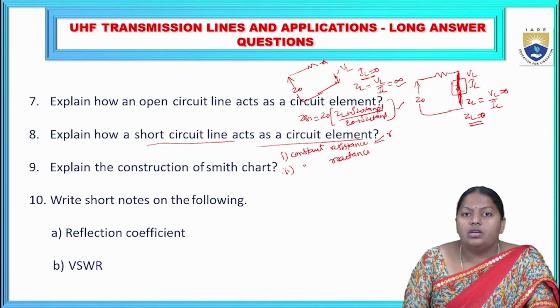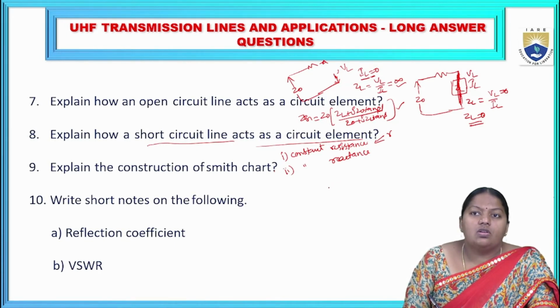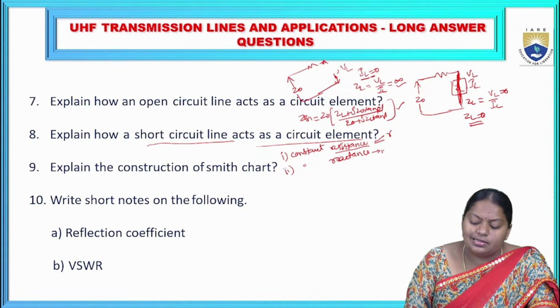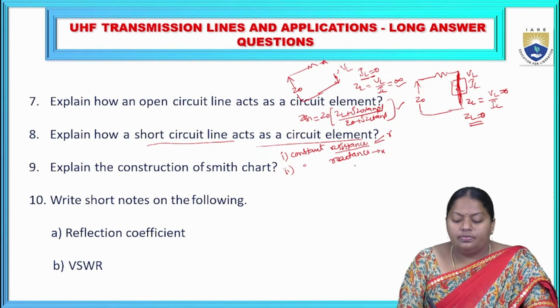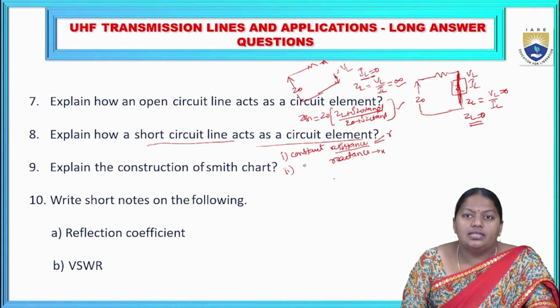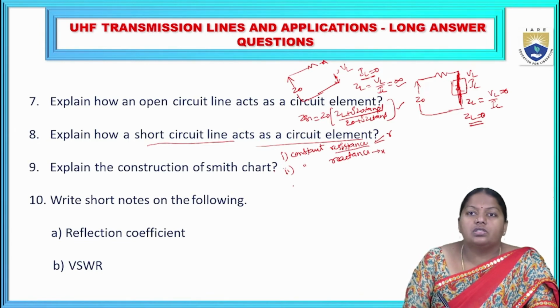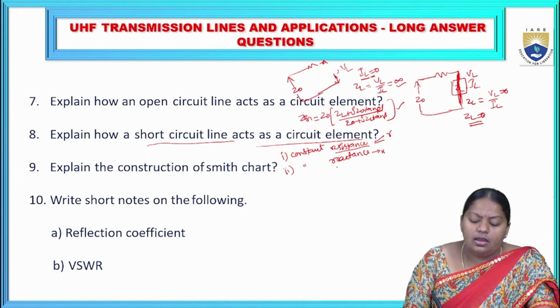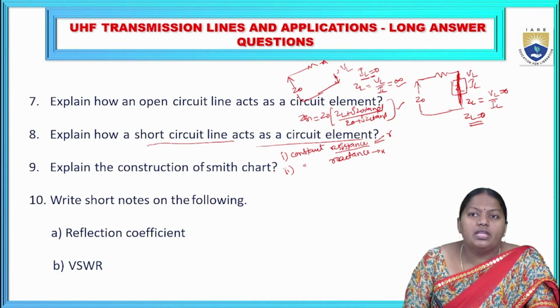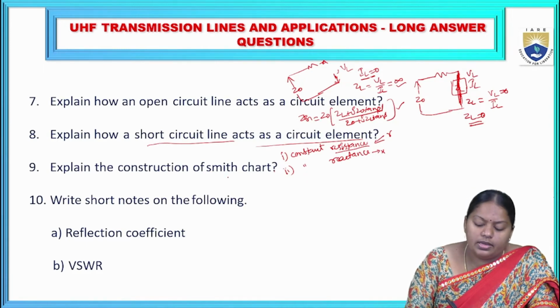At the center, R equal to some value with radius, at some center, we will draw some concentric circles, which are representations of resistance circles. Similarly, for different values of X, meaning the reactance values, with the center we will draw some arcs, which are imaginary lines combined with the circles. Then the graph will look exactly like this.